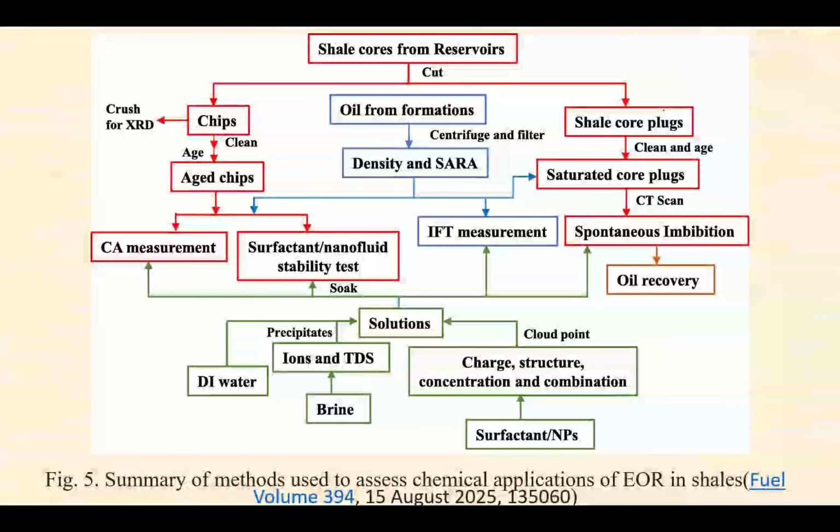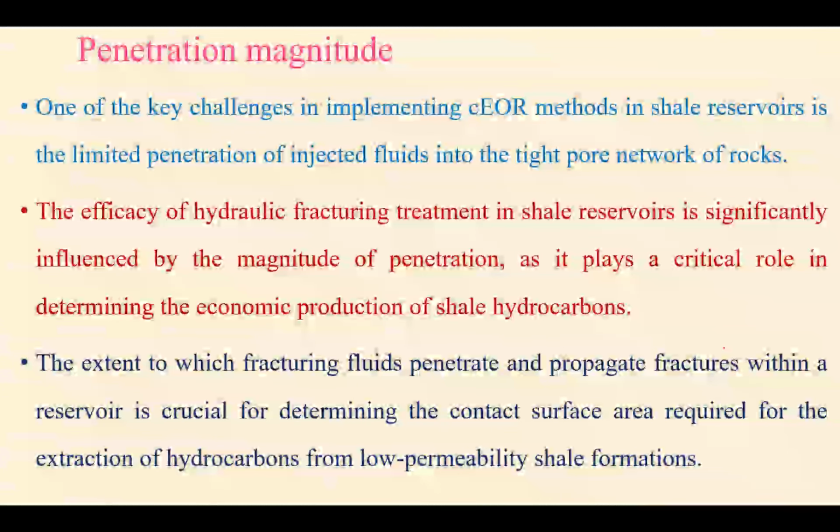So you have to go for rock characterization, crude oil characterization, shale core collection, and the surfactant and nanoparticle composition. Every study you have to perform, and ultimately you have to go for either spontaneous imbibition or forced imbibition, and check what the oil recovery is. So a significant lab study is very much required before considering a plan.